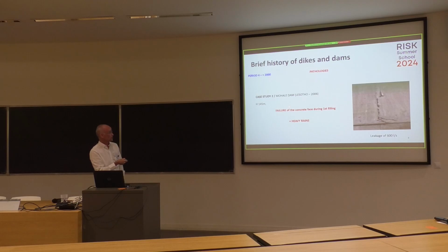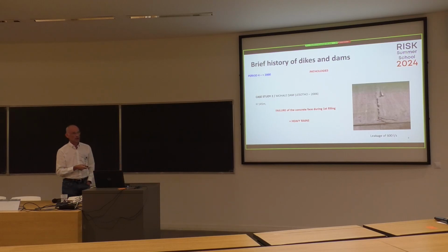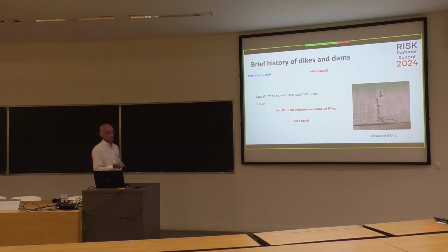Again, the failure of the concrete face occurred during the filling of the reservoir and after heavy rains. So it suggested that water has an influence. Okay? And here the leakage was 600 liters per second through the rockfill.